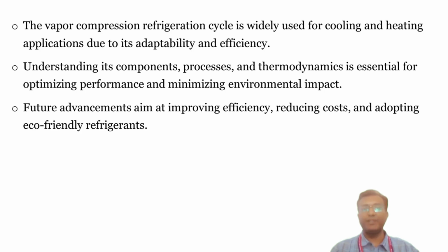The vapor compression refrigeration cycle's ability to move heat using a compressor, condenser, expansion valve, and evaporator makes modern life possible. We have explored its thermodynamic processes, that is, isentropic compression, then constant pressure heat transfer, then isentropic expansion and evaporation, using temperature-entropy diagrams to visualize the energy flow.